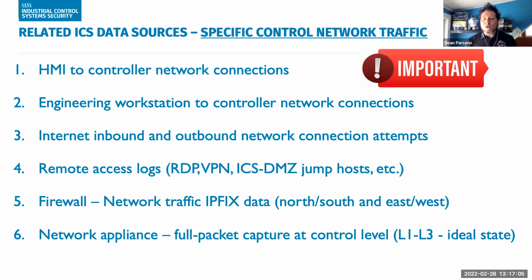And here they are. Generally, when we're hunting, we definitely want to take advantage of at least the 5-tuple or IPFIX or NetFlow data to and from the human machine interface and the controllers in the network as well. So the PLCs and whatnot, to understand what commands are going to the endpoints in the field from the human machine interface, but also the operators, of course, as well.